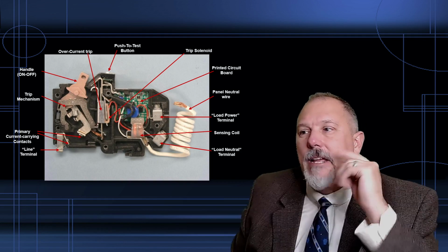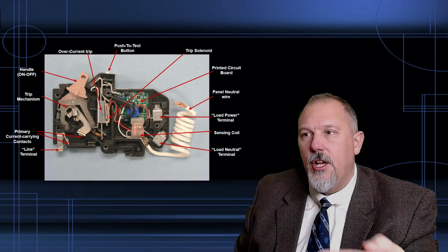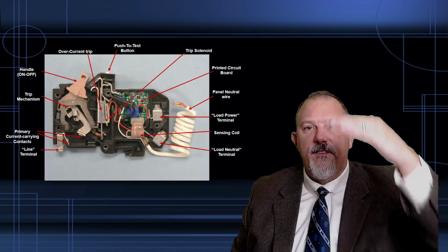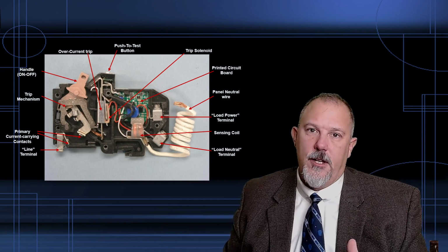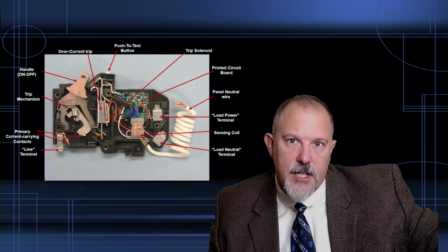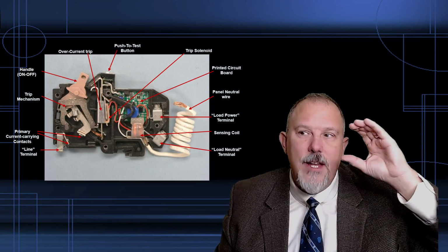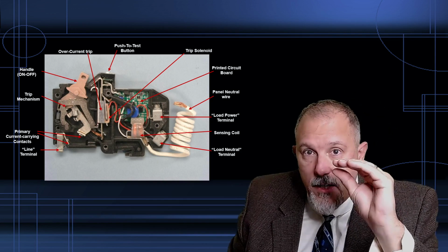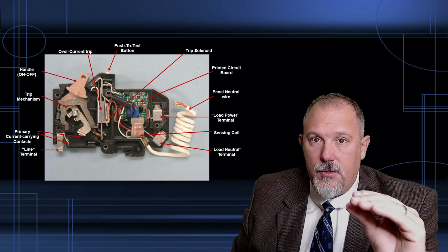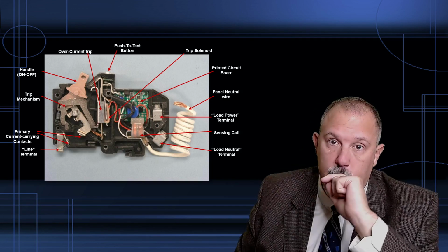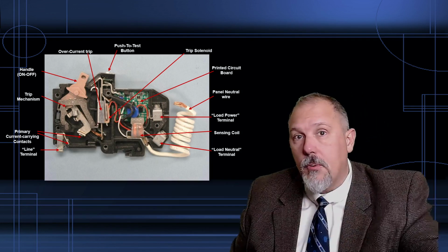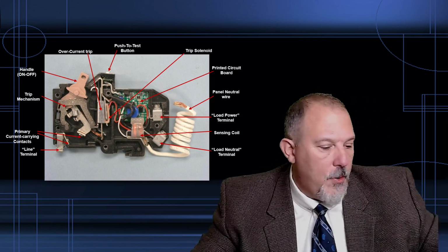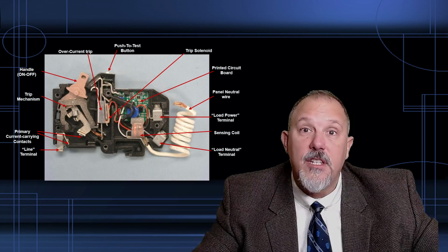If you think about surge requirements or the way we should design surge protection, we want various layers of surge protection. You want the surge protection at your service entrance to knock the peak voltages down to manageable levels that these types of devices can then knock down to even lower levels of magnitude to protect the sensitive electronics. So it's a layered approach and it works as a system. So we're going to walk through this and help you understand how these devices operate and function.